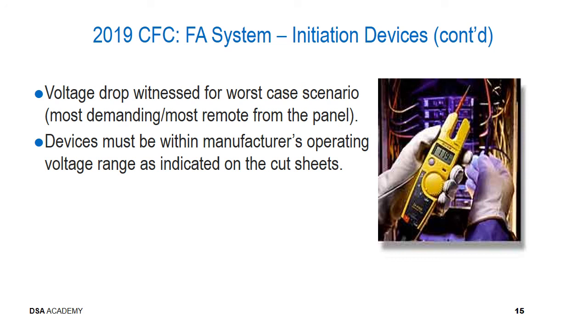Please refer to Inspection Manual subsections 2D and 2E. And it is important when doing this test to refer to the manufacturer's product data sheet and the voltage drop calculations provided on the fire alarm drawings.